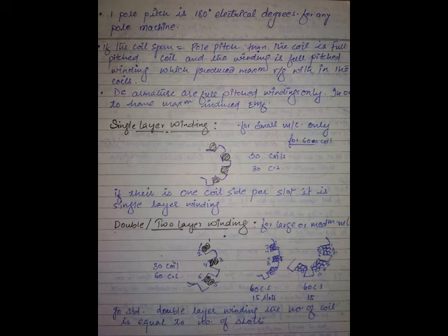In the morning I told you 2 things. There are 2 electrical design constraints. One I told you regarding insulation, and the next one is coming now. The thickness of the conductor, meaning the cross-sectional area of the conductor, depends on current carrying capacity. One constraint is the operating voltage of the system.